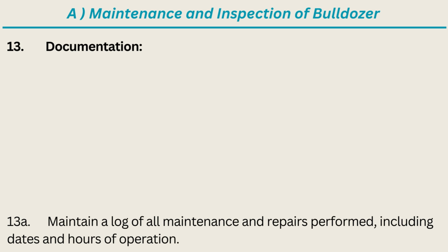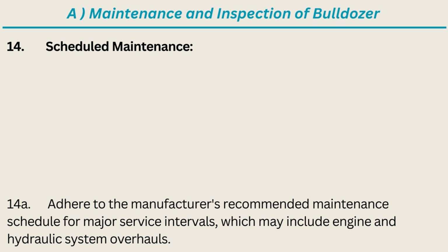13. Documentation. 13A. Maintain a log of all maintenance and repairs performed, including dates and hours of operation. 14. Scheduled maintenance. 14A. Adhere to the manufacturer's recommended maintenance schedule for major service intervals, which may include engine and hydraulic system overhauls.